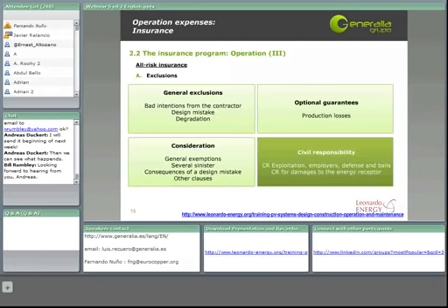Anyway, here we have to say that the main element to suffer degradation would be the solar modules, and as we have also said, this degradation is usually guaranteed by the manufacturer of the modules. To remind you, normally the manufacturers of crystalline modules guarantee that during the first 25 years, a 20% degradation will be produced in the modules.